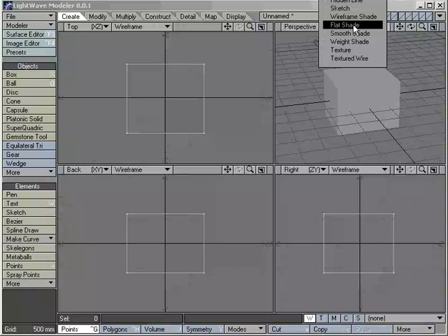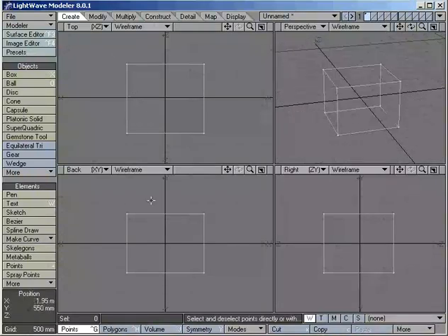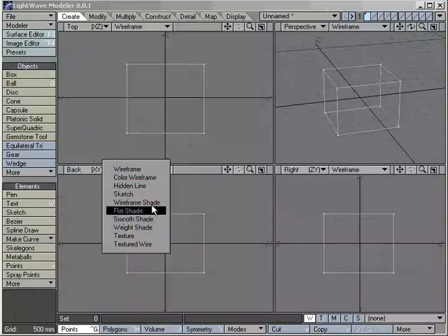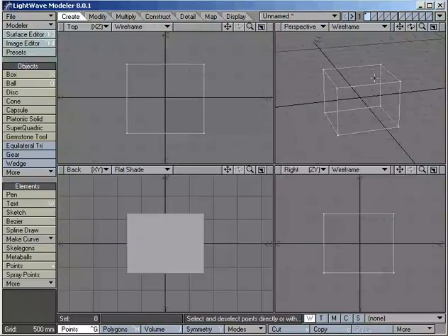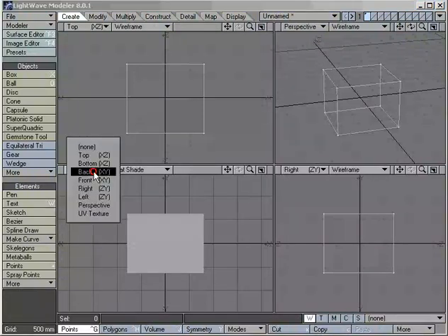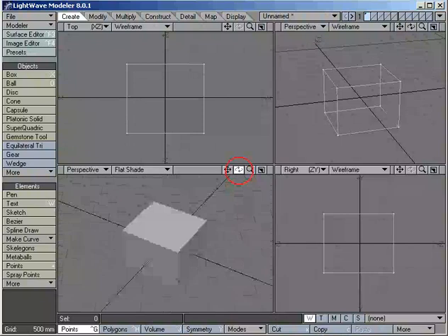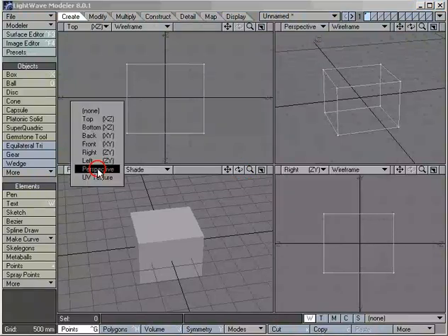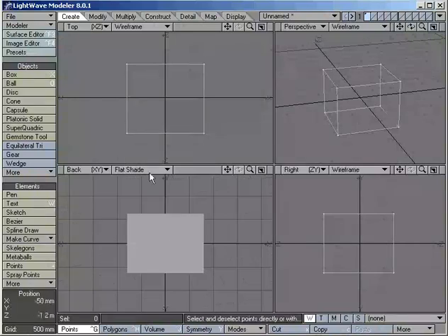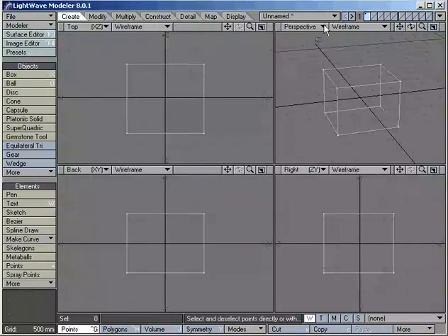This is all the same object. It is being shown as solid because that is the level of rendering we selected. I could select wireframe, so it looks just like this if I'd like, and I could go over here and have this be shaded like this was before. I can also go in and change this one to perspective if I like that better, or if the occasion calls for that. I'm going to go back to back and wireframe, so we're back to the default settings.